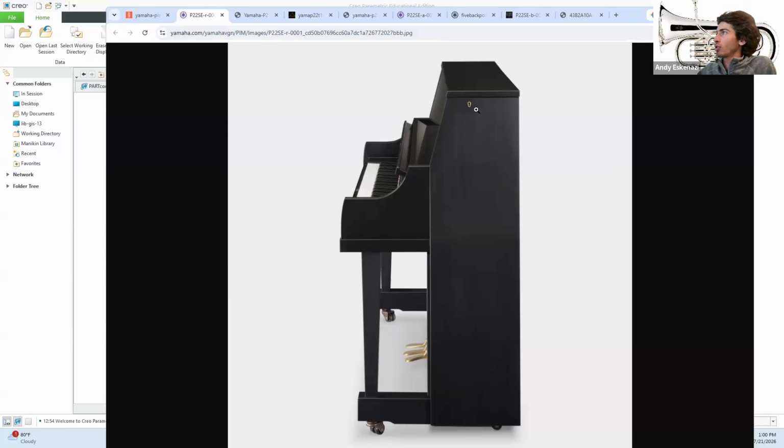I will start by drawing something like this, and we are going to introduce dimensions as we go. We're going to introduce parameters as well. For instance, the height as an example, or this length in here. Then, depending on the complexity and how many different features we have, I may add a few more parameters that we can use to create several configurations of this.